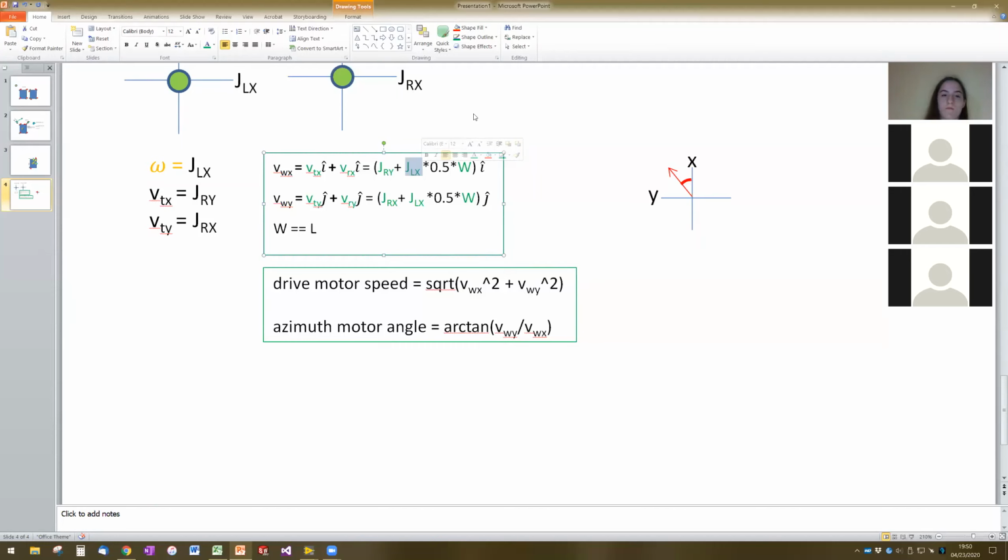Basically, that one's sort of a, okay, so velocity. So it's sort of a little bit of a trick question. The joystick values as they are don't have a unit. They go from -1 to 1, and they're unitless. And so if we were to directly apply this formula, we would have this problem where we're not really allowed to add a unitless number to a number with units, right? If we measured the robot width in inches, we would get a different answer than if we measured the robot width in feet, even if they're both correct values.